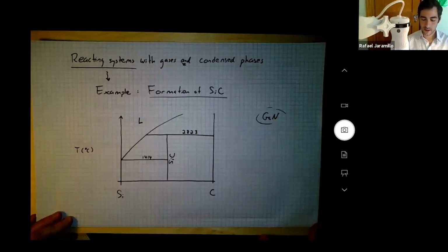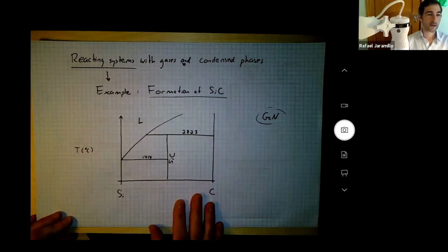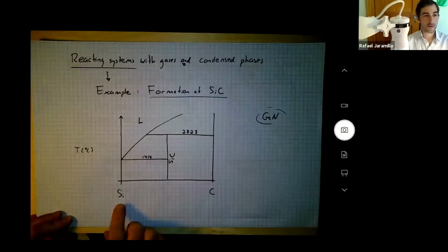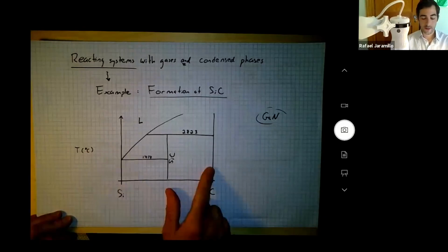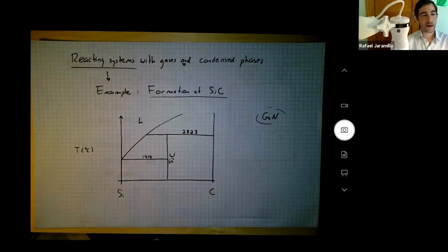And yeah, you might guess that. You might know that silicon carbide and graphite are refractory materials, right? You might know that they're very tightly bound molecular solids with a huge cohesion energy. It's very hard to break them up. And the phase diagram here tells you that silicon is a lot more volatile than either silicon carbide or carbon. It's got a much lower melting point, right? So you might just guess, and I wouldn't ask you to do that, but you might be able to infer that the saturation vapor pressure of silicon carbide and carbon is very low.